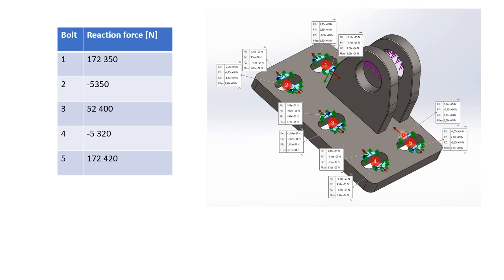And these two bolts basically didn't do anything, and this one did maybe a little less than a third of this one. So be careful, and remember that it is not always correct to just evenly distribute reaction forces around.